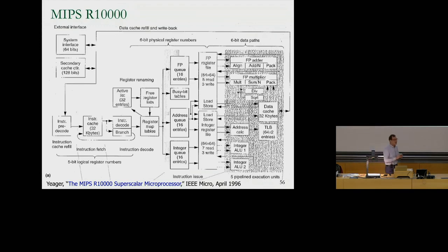So we're not going to have any hardware support for dependency checking or interlocking. MIPS means microprocessor without interlocking pipeline stages. That was their vision in the early 1980s. They wanted to have very simple hardware, and the compiler schedules the instructions. It handles the scheduling so that you don't have dependency issues in the pipeline. And initial MIPS designs were like that.